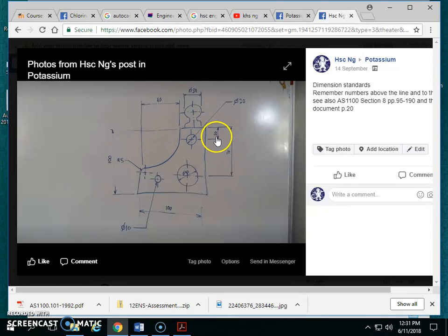There are some things. If we have 2 sets of dimensions, we want to have the smaller one inside the bigger one. There's also requirements for how we do the arrowhead. The arrowhead should be 3 millimeters long and 1 millimeter away from the line. And that we should have a 2 millimeter gap between the object we're drawing and the thing we're dimensioning, and that 2 millimeter gap should also extend past our dimension arrow.